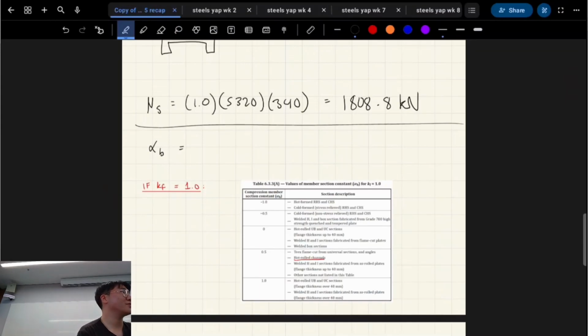It's going to purely be based on a yielding, crushing kind of failure, right? And same thing if I had a stick that was the length of this whole room. I push down a little bit, you're going to see major buckling effects. So that length is going to have a kind of quadratic effect on how much strength we have, because it's going to be governed by buckling now, right?